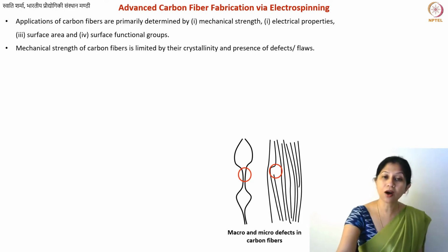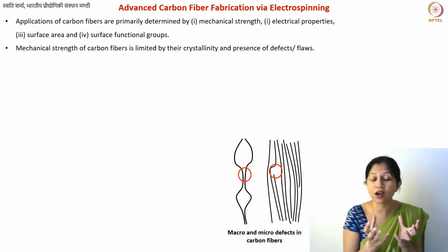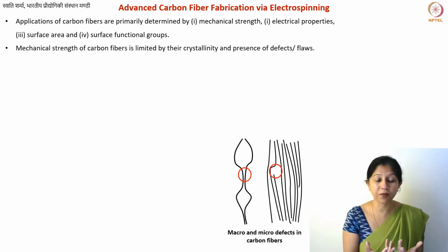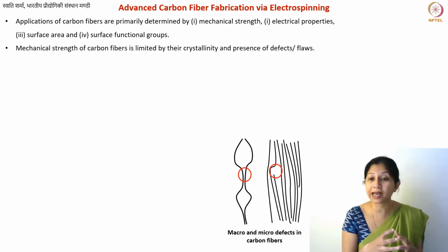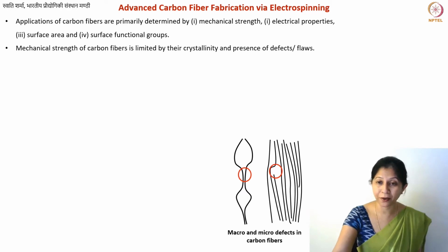Okay, if you look inside a transmission electron microscope at the microstructure of your fibers, you can also have, like I have shown again with a circle, regions where you do not have any graphitic planes. You can call it an amorphous region. You can call it a region with randomly oriented, random bond lengths of the atoms, but you do not have sp2 type hybridization, and you also do not have any graphite crystallites.